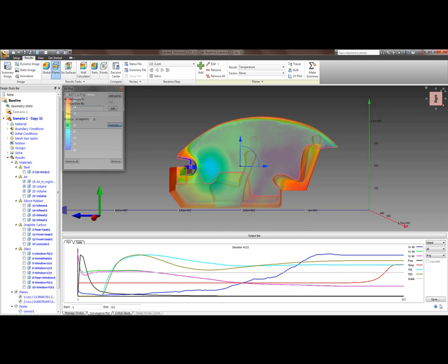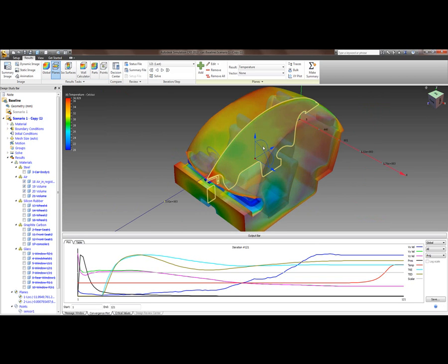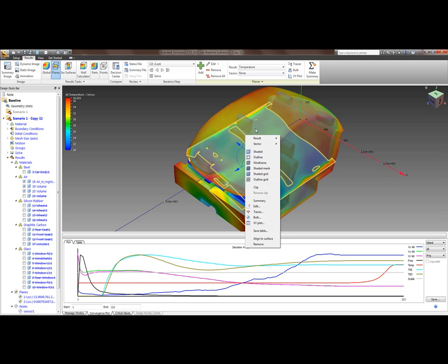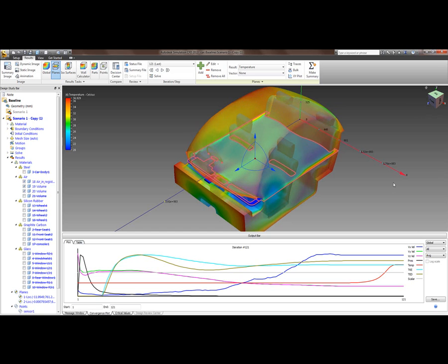Now that we've traced the area and put some points in, we've established where they are on the X and Y plot. We now know the temperature going up from the bottom to the top, so the vertical temperature change. Now what we want to do is change this plane around, so I'm going to change the view slightly, and I'm going to use the control features on this plane to take a flat view. So let's put that like that, and let's make sure I put it on the Y plane, like so.